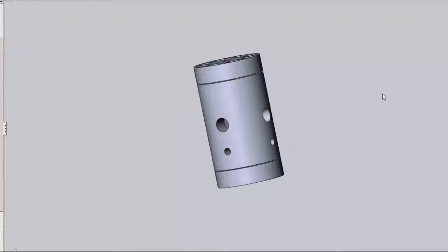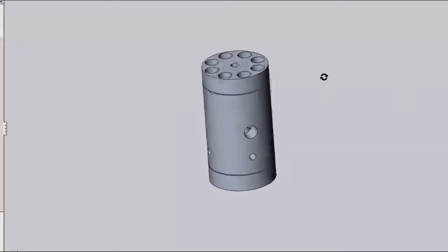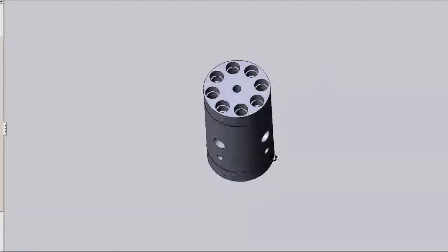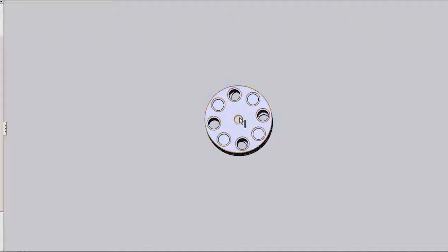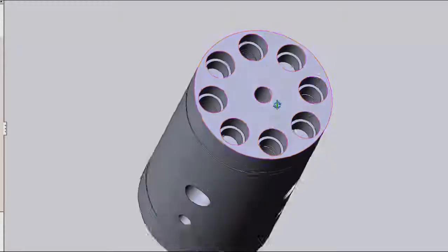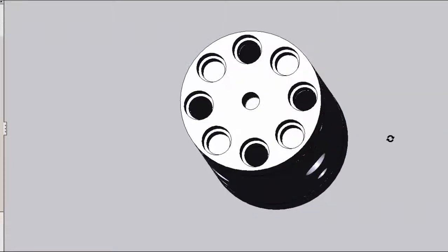So the anvil cell was limited in size by the probe, which is dipped in liquid helium, and the anvil cell has to be attached to it. So there's a strict limitation on the diameter. Then each of these holes had to be specifically sized so that we could fit 4 millimeter screws in them, which is enough to withstand pressures up to 100 kilobar, given that the screws are under tension when the anvil cell is placed under pressure.